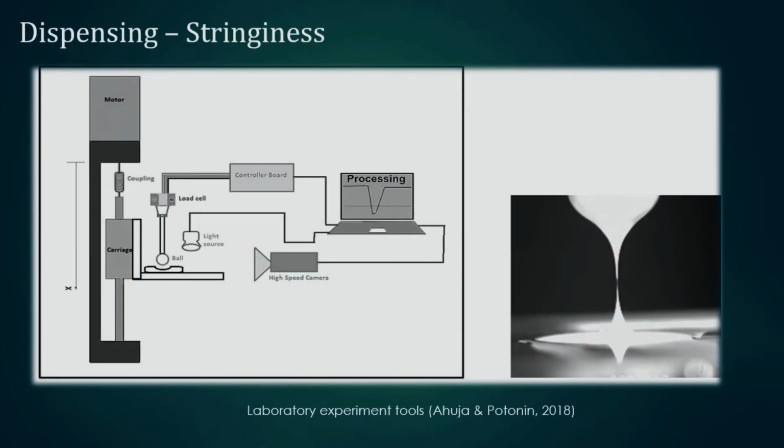The stringiness test is a practical method of measuring the adhesion and cohesion properties of a paste and is directly related to viscosity. A high stringiness value indicates that a paste will not break easily, resulting in poor ribbon formation as the user finishes extruding paste from the tube. Stringiness not only affects the consumer, but also affects the production line, which operates at high speed settings.